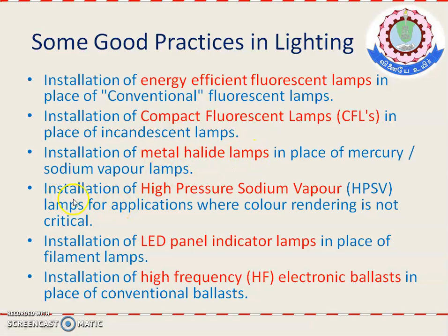And wherever you have a requirement of low color rendering, in such cases you can go for high pressure sodium vapor lamp, which has a high efficiency as well as high lifetime. And in night lamps, you may see that there is a filament which consumes around 5 watts or more, and that filament can be replaced with LED panels.